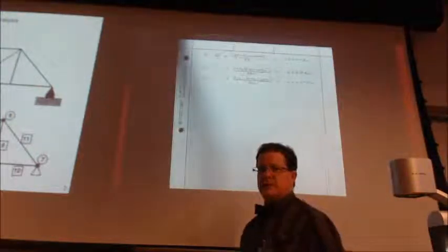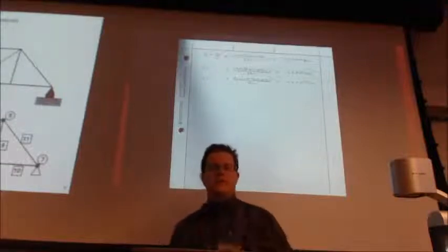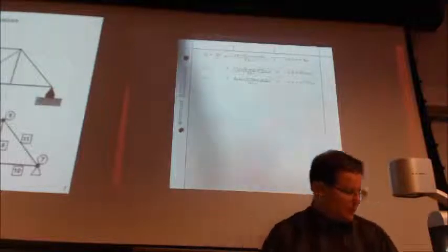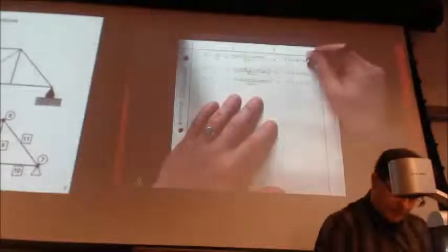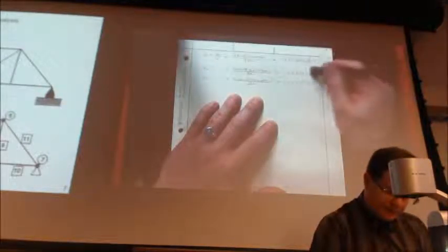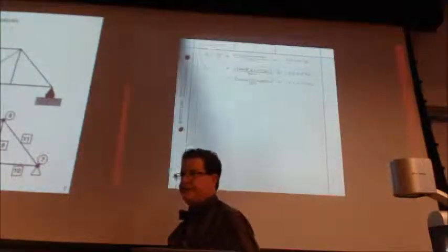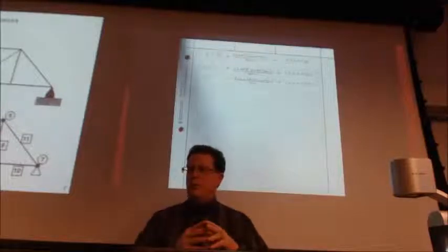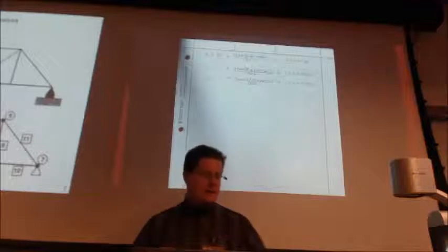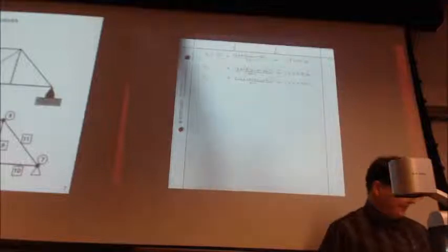Okay, so does that make sense to everybody what we're doing? Because we're going to treat these. So are your units for K psi? Pounds per inch. Oh, not square, sorry. Pounds per inch, because it's a spring constant. So we're treating our truss like a spring element, and this is going to be the stiffness of our spring, our K, for our truss element.